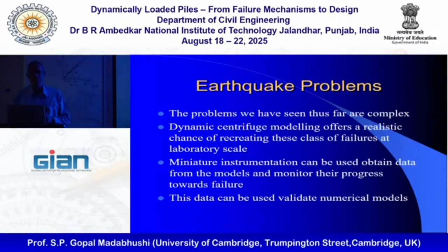One of the big advantages of centrifuge testing is that we can put in instruments and see what is happening before the earthquake, during the earthquake, and also after the earthquake, which means we can track the movement of the structure towards failure. And then you can also use this data to validate numerical models. So you have quite a lot of advantages.